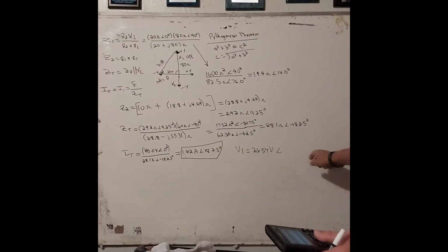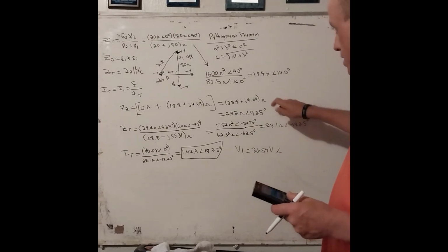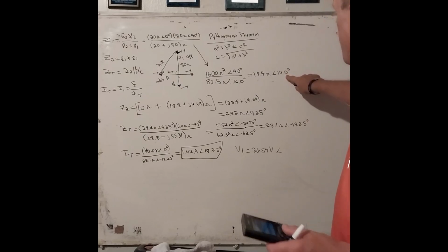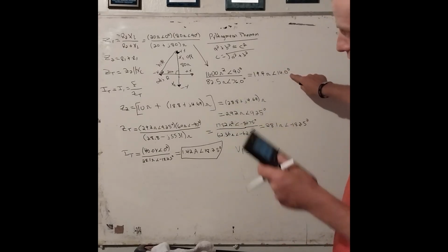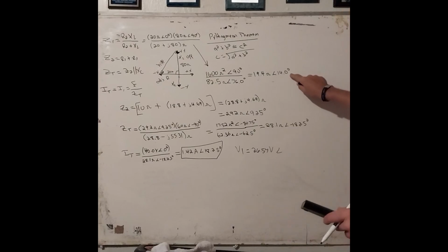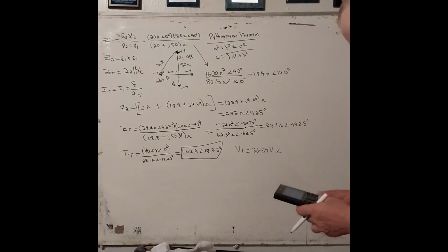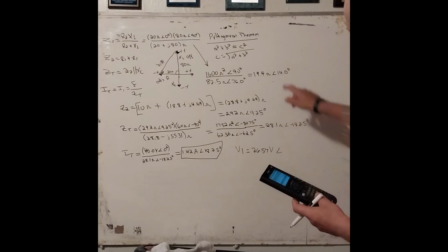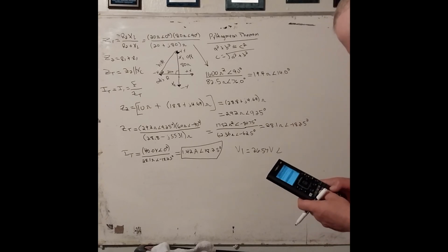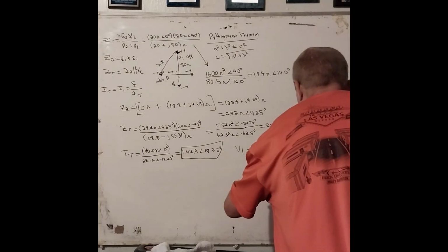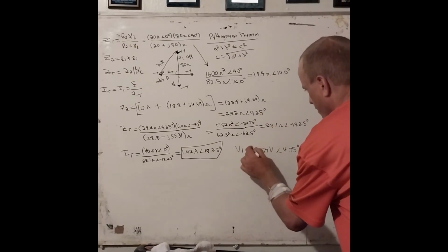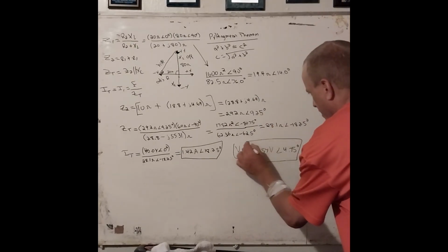That value is multiplied by Z sub 1 to get the voltage drop across the X of L. And we take negative 9.25 and add that to the 14, and we get 4.75 degrees. So this is the answer for the second one, V sub 1.